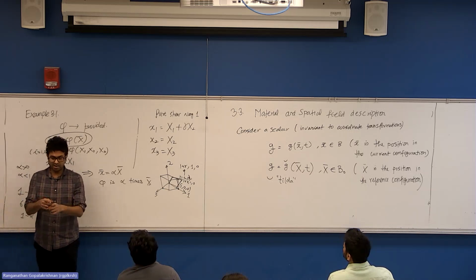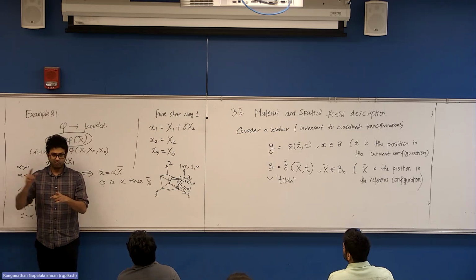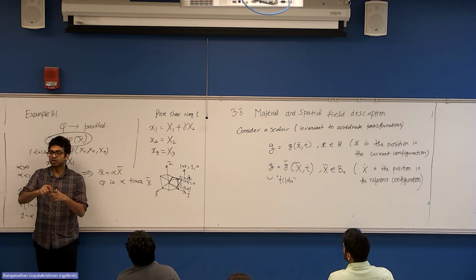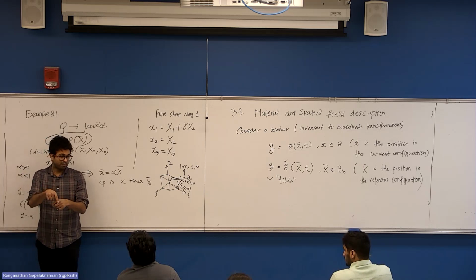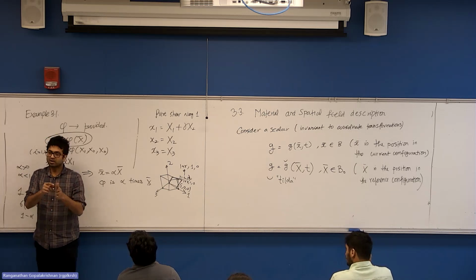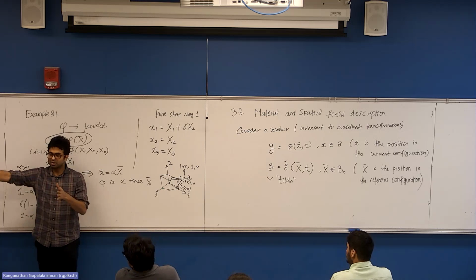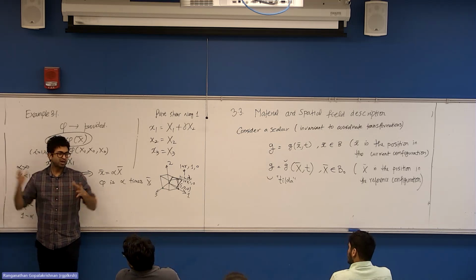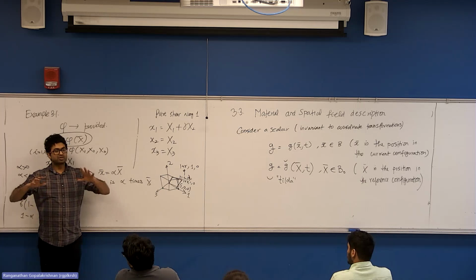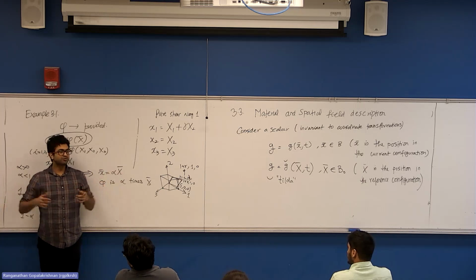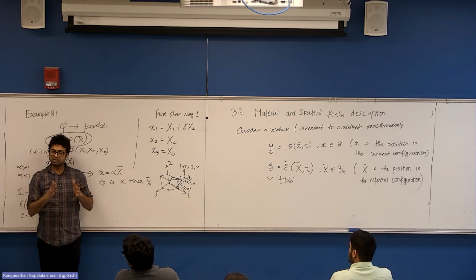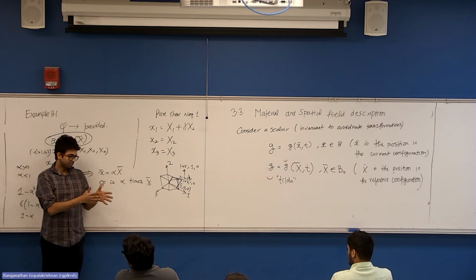So if you drop your dye at T0 and you observe this for the next 10 seconds, whatever fluid molecules were there at that point when the dye was dropped, they are the ones you are tracking for the next 10 seconds. I'm not interested in that place where I dropped the dye. My focus is always on where the dye is, where the molecules are. I'm tracking each of them. That is the analogy where I said, instead of focusing on who is here, I start tracking each of you individually after you leave, or from now until some time. That becomes material or Lagrangian.